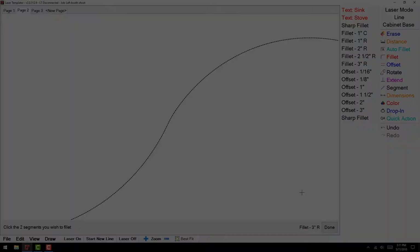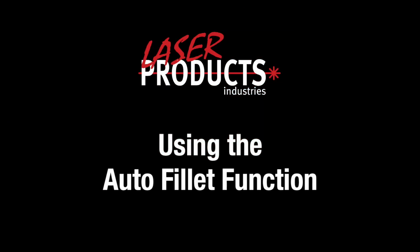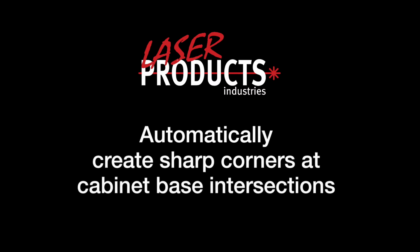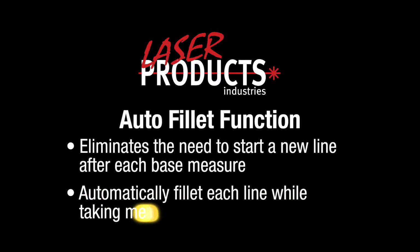Quick Action button. In this video, we will be showing you how to use the Auto Fillet function, which will automatically create sharp corners at cabinet base intersections as they're being measured. Using this function eliminates the need to start a new line after each base measure, as well as having to go back and fillet each line together after the measurements are taken.